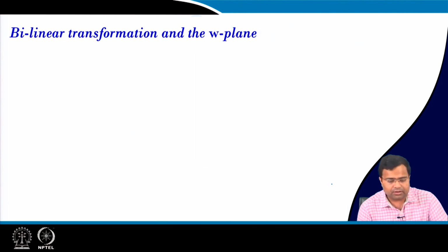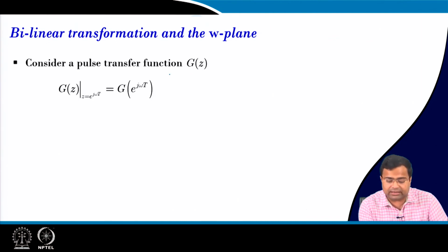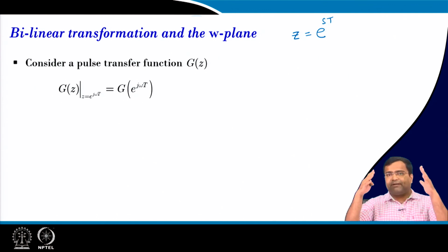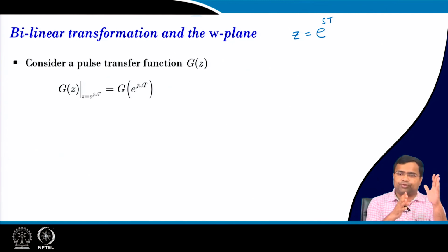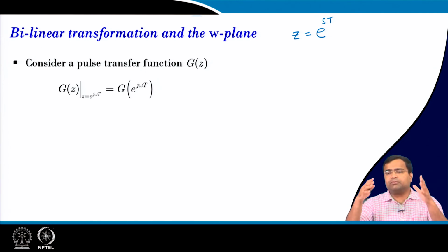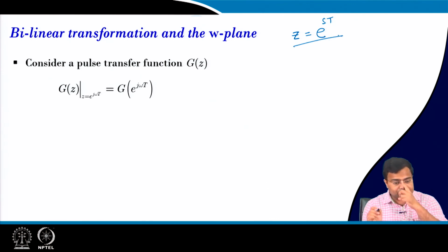Now, this bilinear transformation gives you a Z domain transformation. That is called pole-zero mapping, it is Z equal to e to the power sT. That is the exact mapping, and that comes from the fundamental Laplace transform theorem. That means if you go for how to obtain the transfer function using Laplace transform, and then go to the Z transform by two basic theorems, you can relate Z equal to e to the power sT.